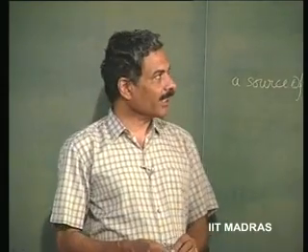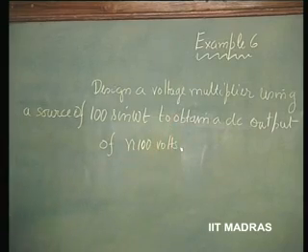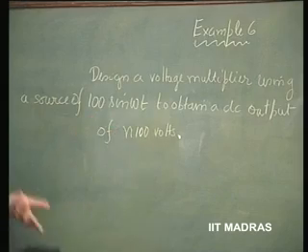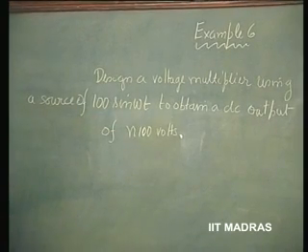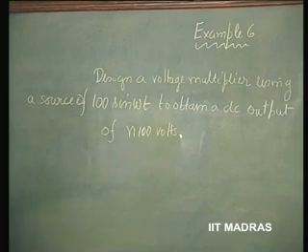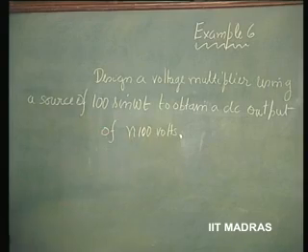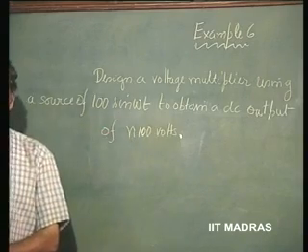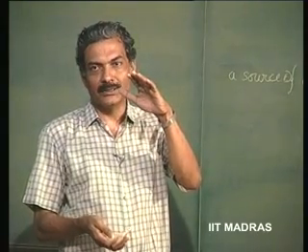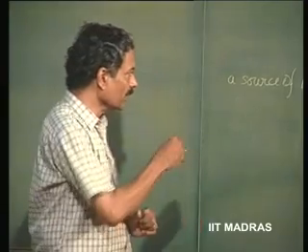Today, we will take an example. Design a voltage multiplier, that is, let us say an AC voltage of 100 sin omega t, from which you derive a DC of 100 and then multiply it by some amount n, 100 times n being an integer. So, how can this be done, and how can this be utilized in obtaining what I told you last time as an ionizer, in order to obtain a high DC voltage which can be used to produce a negative ion effect? Let us see how this can be done.